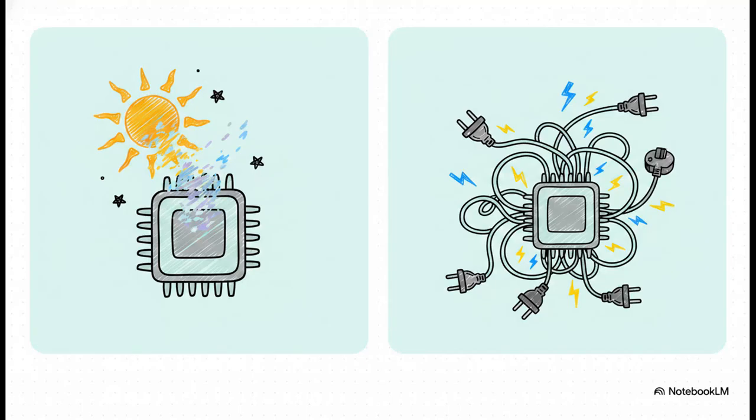Let's look a bit closer at those middle steps because it's truly amazing to think about. Early rewritable memory, EPROM, literally had to be exposed to actual ultraviolet light to dissolve the charge on its transistors. You were blindly wiping all of its data at once. Thankfully, EEPROM came along and gave us the ability to erase and program data electrically. Though, to be fair, it did require some pretty complex circuits using different voltages for reading, writing, and erasing.